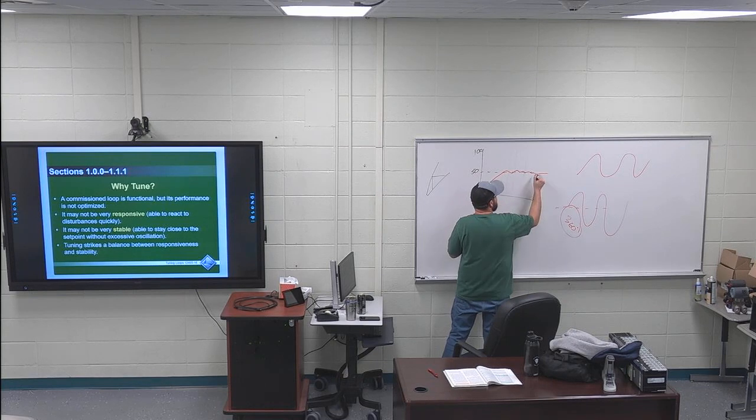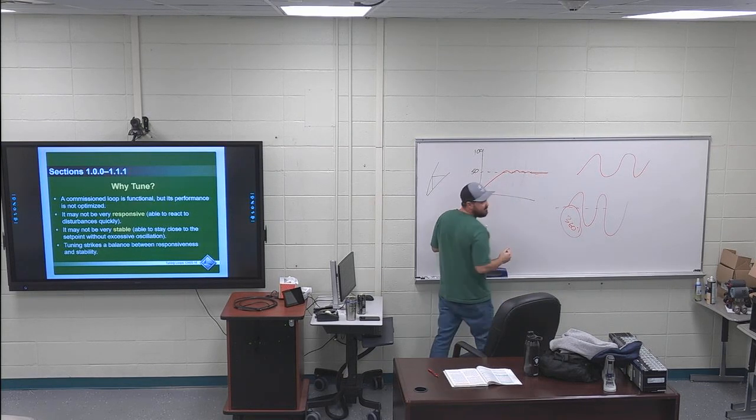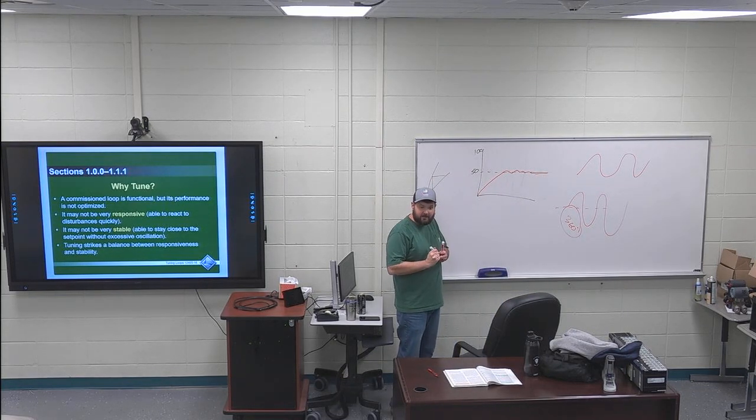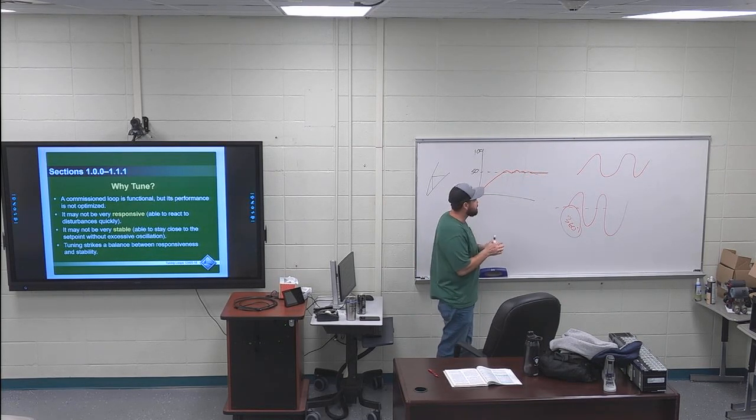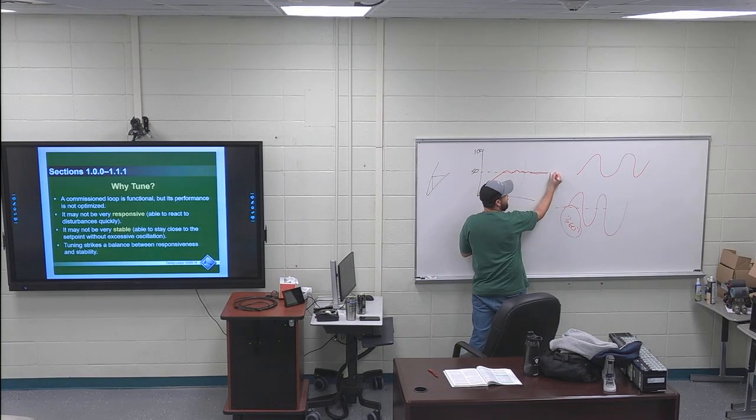If I continue this line out here, it's pretty dang close, but like I said, big tanks, half an inch off, doesn't matter. But there's still a minute amount of error once you try to get to that set point. Integral control takes care, literally, of just that.